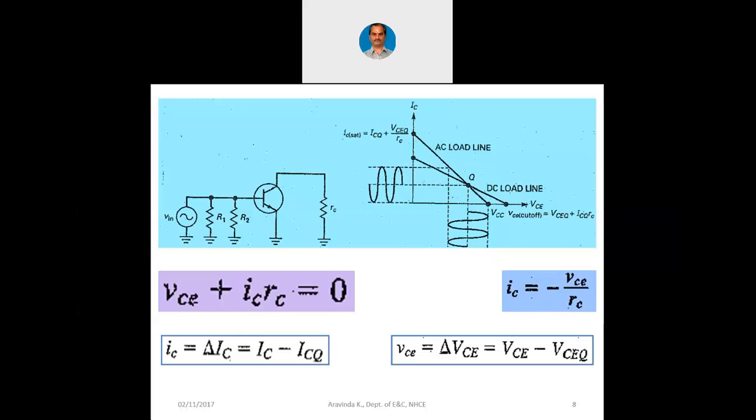We are discussing power amplifiers, and now the input signals are not small signals, they are large signals. Input signals also have enough power now. When they have enough power, the base current is predominant now, unlike the earlier case. Earlier, when we analyzed circuits, we used to ignore the base current with respect to the collector current. Now in power amplifiers, the base current cannot be ignored with respect to the collector current. So that is how you can see there is an increase in the saturation current.